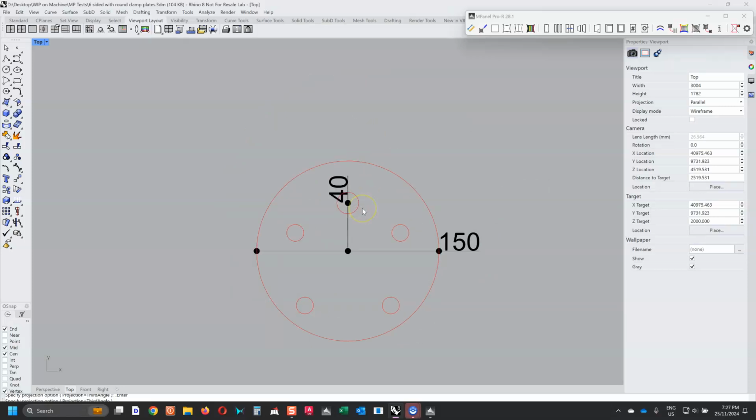If we wanted a tensioning device length between the post and the clamp plate connection of say 300 millimeters or 12 inches, we need to take into account the fact that MPanel works to the center of the clamp plate, not this point here.